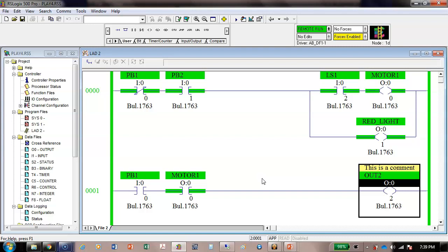So we wrote our first program, or I wrote it for this PLC. This is RSLogix 500. This over here is called the project tree. We'll explain this. Most PLCs have that. This up here is the instruction palette. All of them have that, where we can pull instructions into our program. The palettes will be, here's bit, by the way. User is where you put the instructions that you use most often. So instead of having to go through all this palette and find this jump instruction, which is way out there, I can put it into my user palette, and now I can use it real fast.